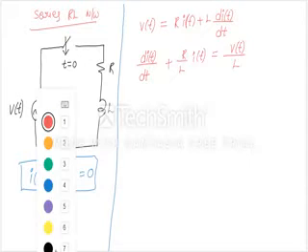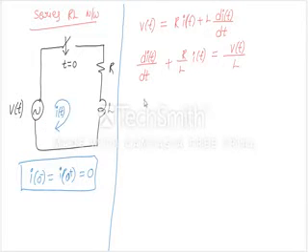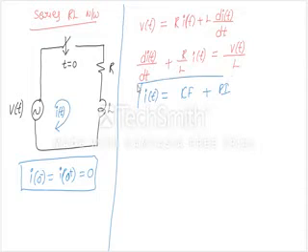So we need to find the solution of this equation. The solution for this I of t is given as CF plus PI, complementary function plus particular integral. Let us find the complementary function first. For the complementary function, we should make the right side value 0.